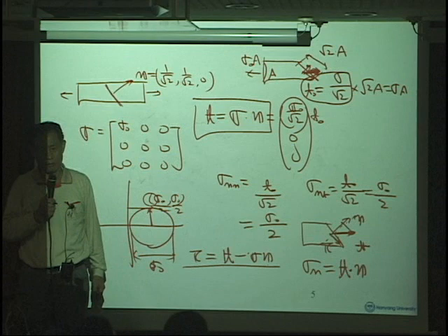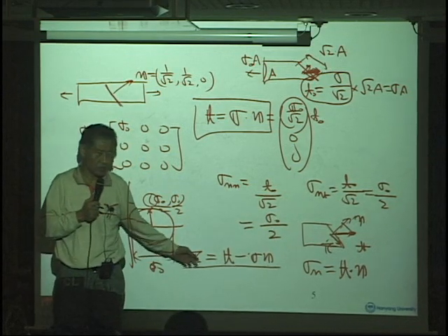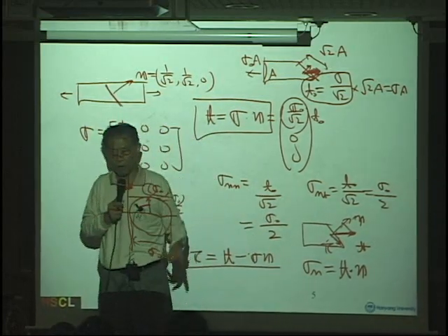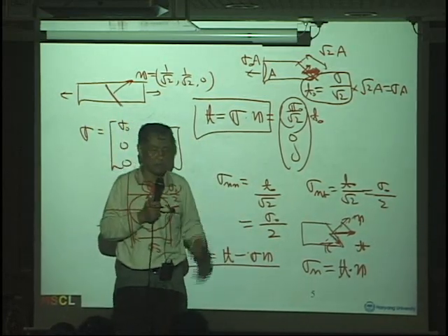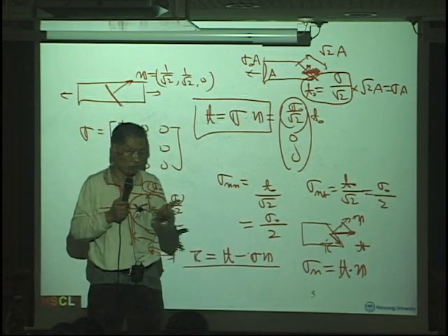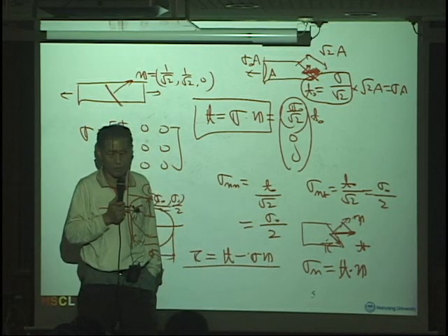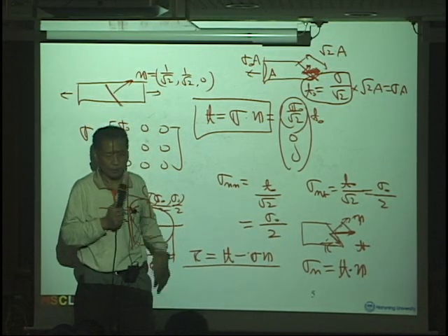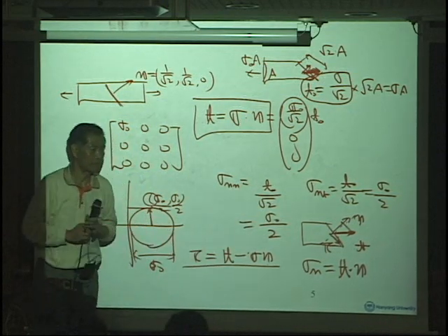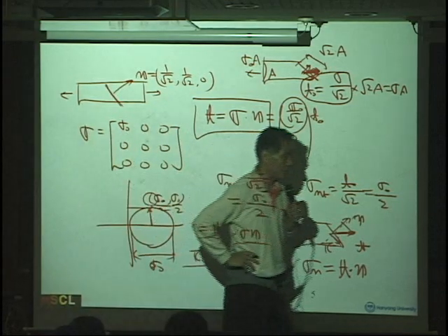Again, this is the shear stress, and this is the normal stress, and you can apply this equation to a three-dimensional stress state. You can certainly try it on your two-dimensional case and make sure you get the same result as the Mohr circle. Okay, anyhow, that's one thing.